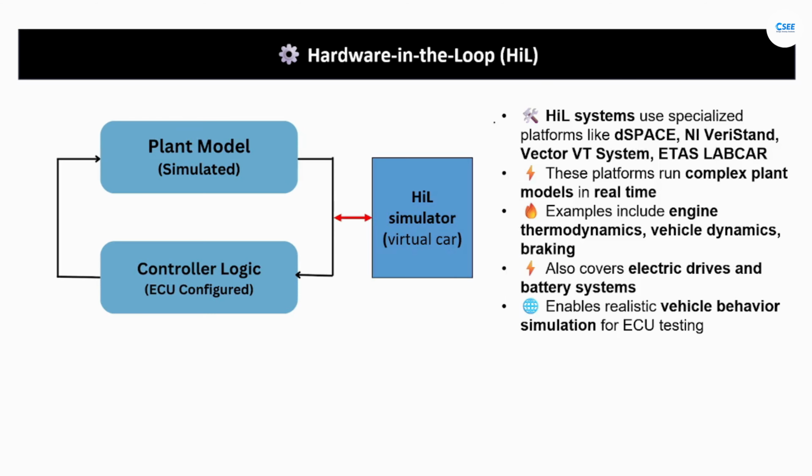HiL systems are typically built using specialized platforms like dSPACE, NI VeriStand, Vector VT systems, or ETAS LabCar. These platforms can run complex plant models: engine thermodynamics, vehicle dynamics, braking, electric drives, battery systems, all in real time.